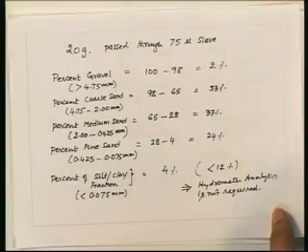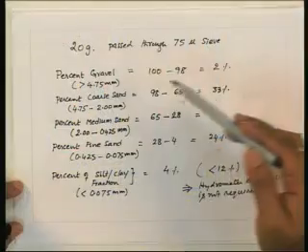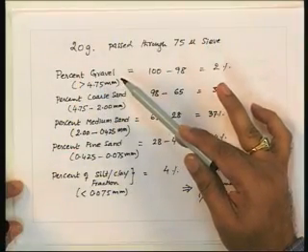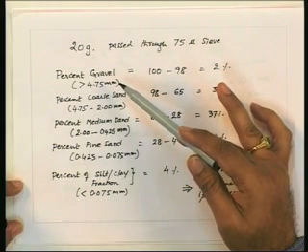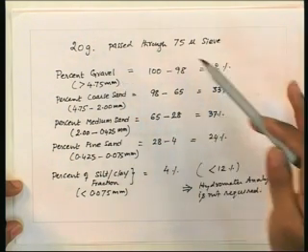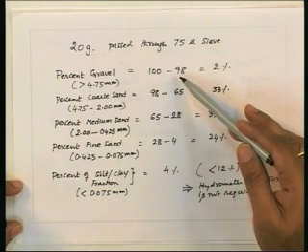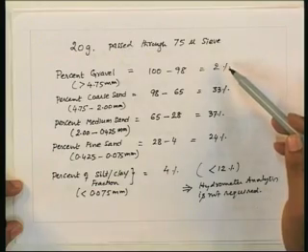Let us look now, as we noticed that only 20 grams of soil passed through the 75 micron sieve. To calculate the percentage gravel, that means gravel size particles which are greater than 4.75 mm, we take 100 minus 98, which gives you 2%. It indicates that 2% of the soil mass has gravel size particles that are greater than 4.75 mm.